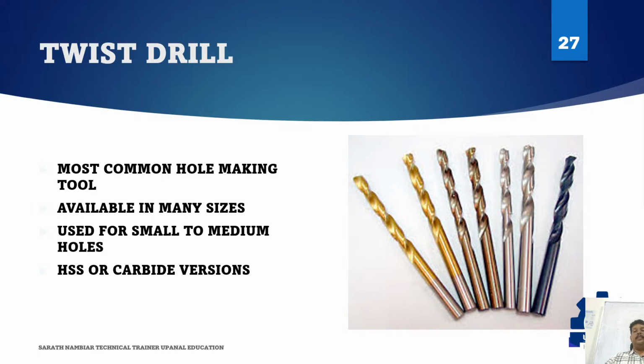Even though it looks basic, drill selection still matters. Wrong speed, poor coolant, weak clamping, or a dull drill can create oversized holes, heat, and breakage. So, never underestimate drilling. Hole making is one of the most frequent operations in a machine shop.